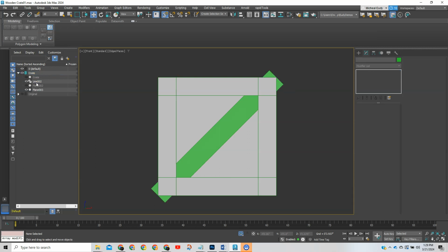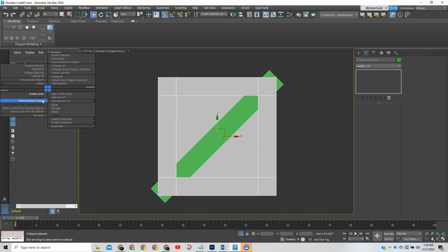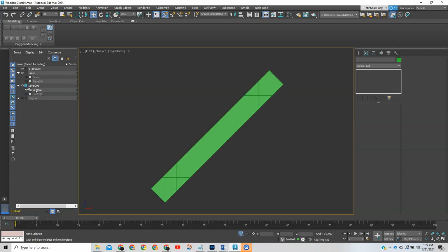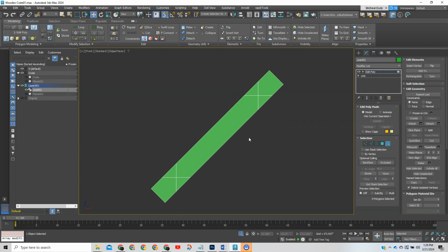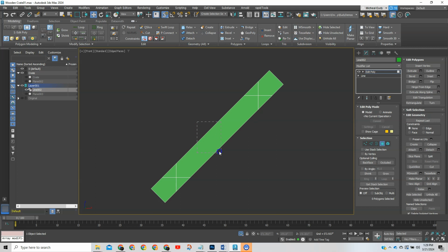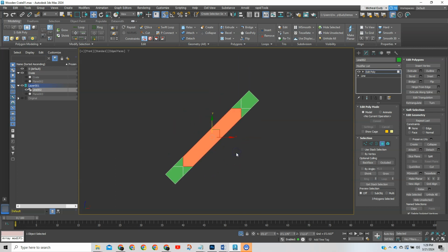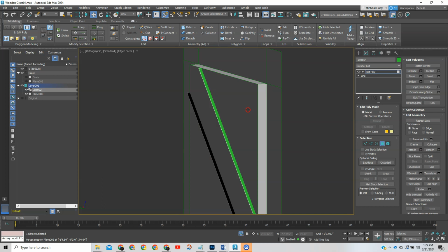Let's put these on their own layer, create a layer for them. Okay, and now we'll see that this line is cut. So what we want to do is go to borders and select this inside. Now you can't just pick it because it's got depth to it. So you have to drag across it to pick it, then invert that selection, Control I, and hit delete, and it'll delete those excess. And so now that perfectly matches and goes inside of there.